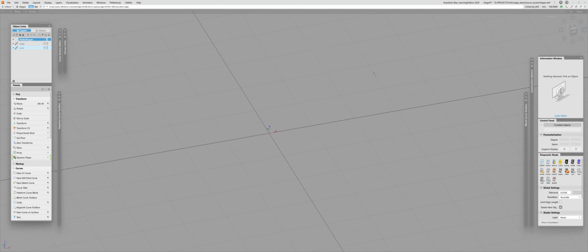Okay, first of all, what are these options for? Both of them, the edge and skew, are designed to constrain an infinite amount of surface boundary directions within the desired continuity. In most situations, alignment may have plenty of solutions, and edge and skew are designed to define them. Edge align options in particular are designed to constrain edges of the surface to be parametrically aligned to the isoparms of the surface, not necessarily to the edge of the surface.